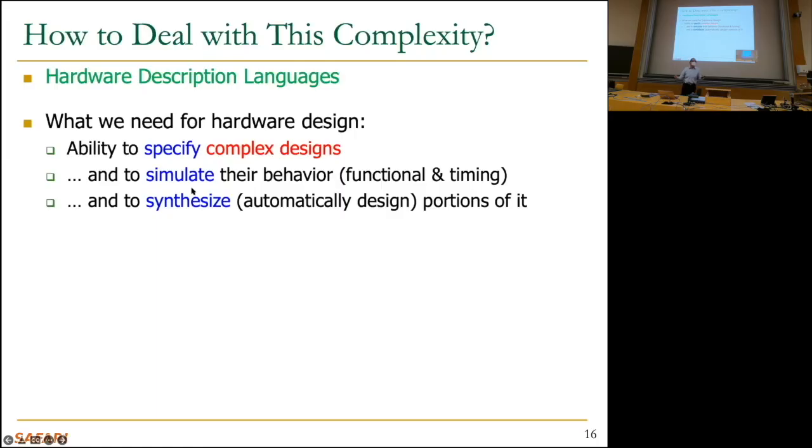So this sounds very powerful, right? You write your hardware description in a higher level language, and that enables you to specify, simulate, and synthesize. And these are the three major goals. Well, why synthesis, you can say, right? Synthesis is interesting. Why not actually design, again, everything by yourself? Synthesis, enabling automatic design, is good because it can get rid of errors in your implementation. When you design something by hand, even if you're using a hardware description language to go ahead and implement it later on, you may have errors.